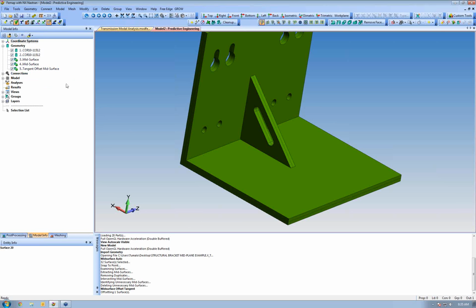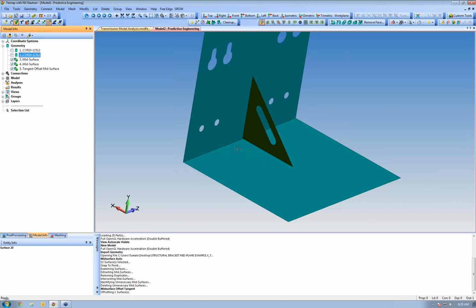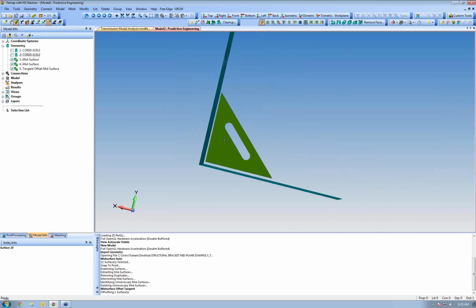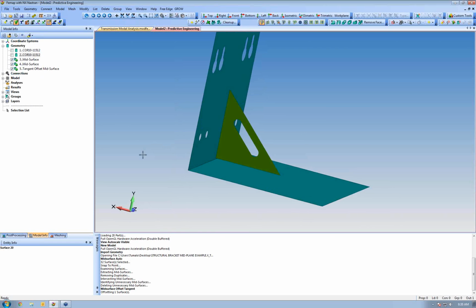Now, what I really want to emphasize here is the capabilities of blanking things in your model. Where before we would have to use groups for everything, now we've got a quicker and easier way to turn things on and off. There you can see I've turned off the original solids, and they're not in a group, they're not deleted or gone, they're simply hidden from view.